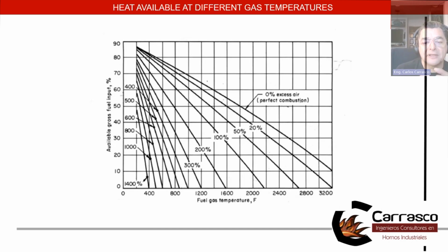But what is not being burned there will be burned in a second stage and probably a third stage of the combustion process. So most of the time, engineers design combustion systems adding a minimum of 10% of additional combustion air to burn the excess fuel that has not been burned during the process.